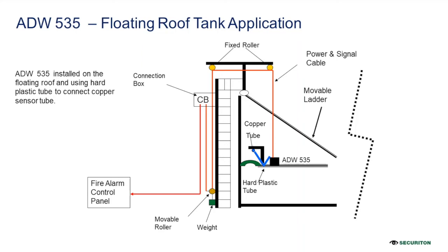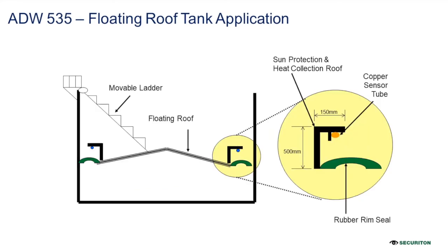When the roof tanks are being filled, the roofs may go up and may go down. So you must keep a provision in the cables so that they fluctuate according to the needs of the roof tank. That makes sure you don't have any obstruction, with signals being cut because the cables got damaged. So this has to be taken care of when you do applications on a roof tank.